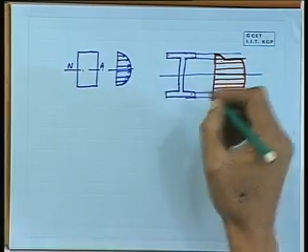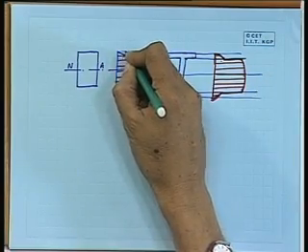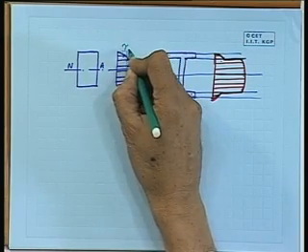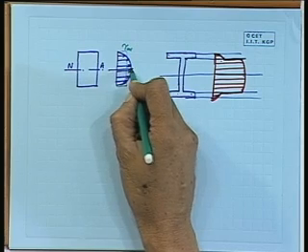Okay. So up to this, if you have any questions, I think you can ask me. This is very important. That's why I said right in the beginning, if you take the total shear force divided by the shear area, what you get is the average. And when we say the average, this is what is tau average, and this is what is your tau max.